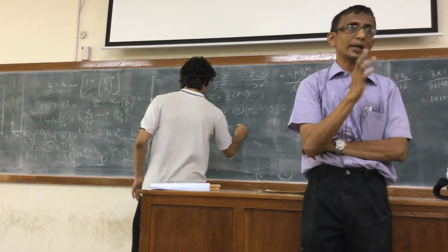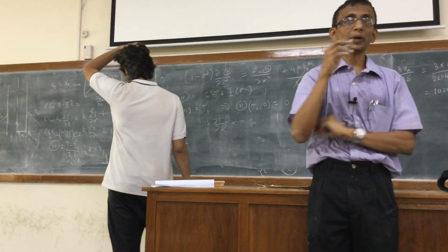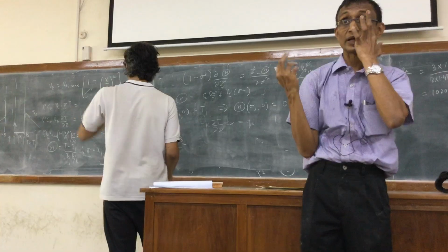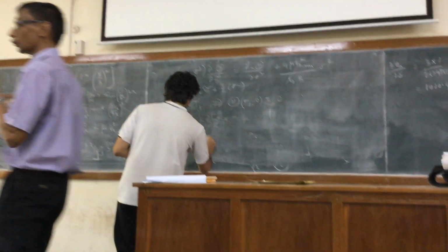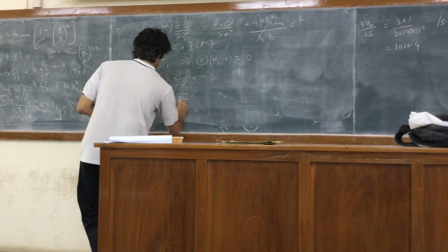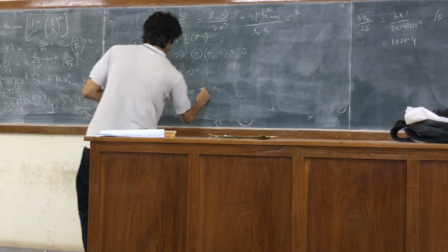There we had r equal to Rc with one boundary, and we imposed a finite temperature at the r equal to 0, which we later on used, Rc equal to 0. Here it's slightly different because there are two boundaries at x equal to minus b and x equal to plus b. There it was at the center of the cylinder.